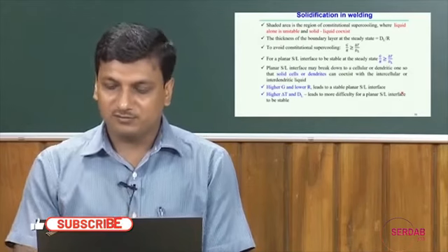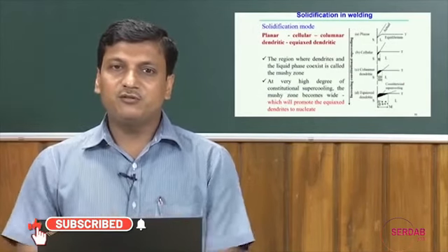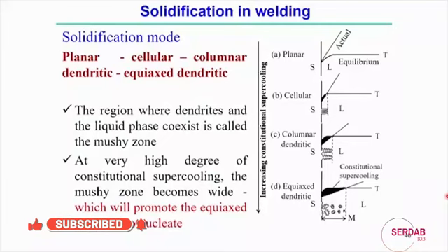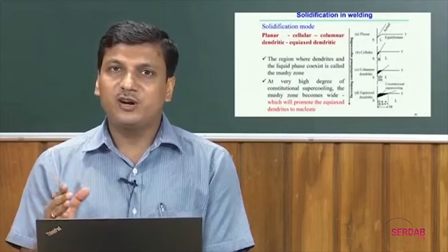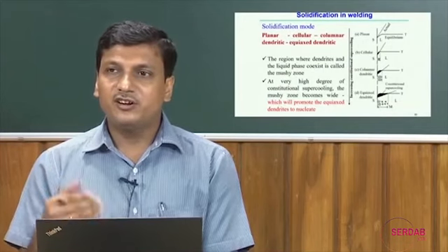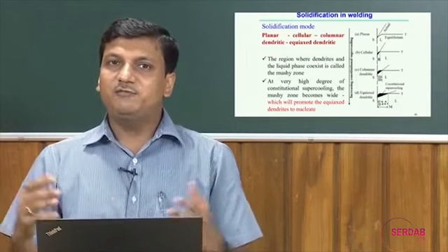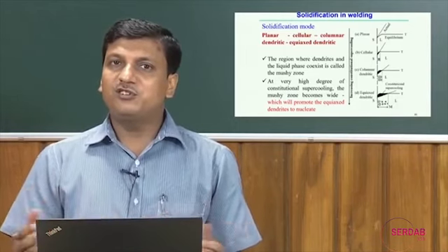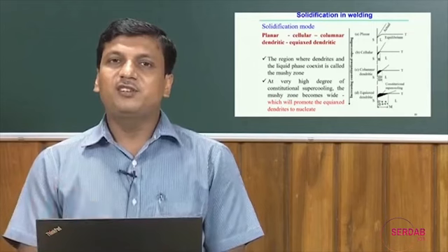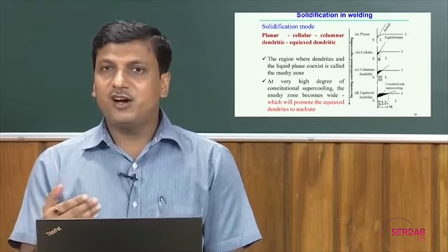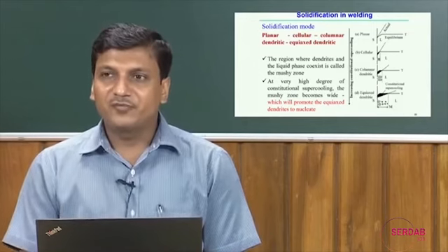Solid liquid interface. Now, here we can look into the different types of solidification mode and structure. It is also necessary to mention that these two parameters, G and R, that means temperature gradient and growth rate, actually mathematically define the mode of the solidification, and at the same time also define the rate of cooling.